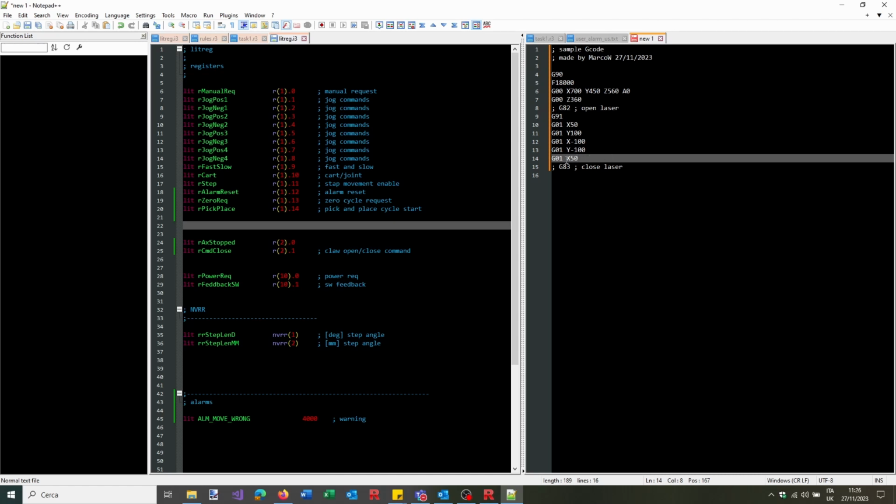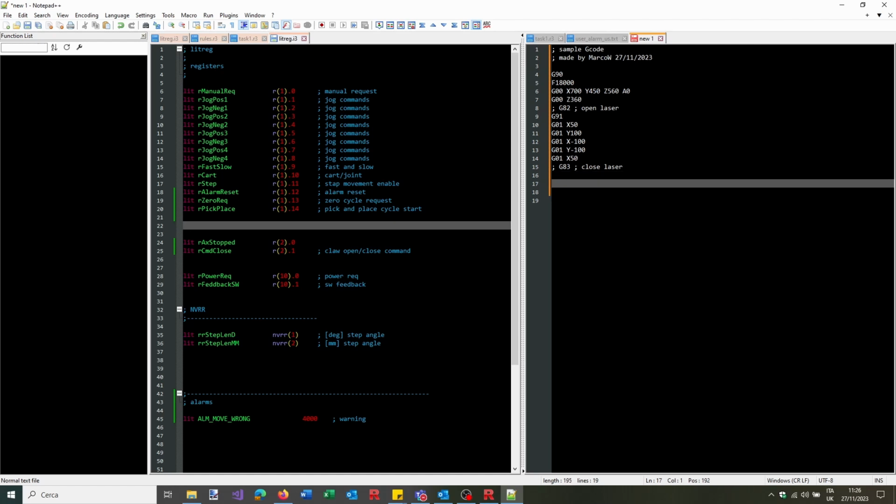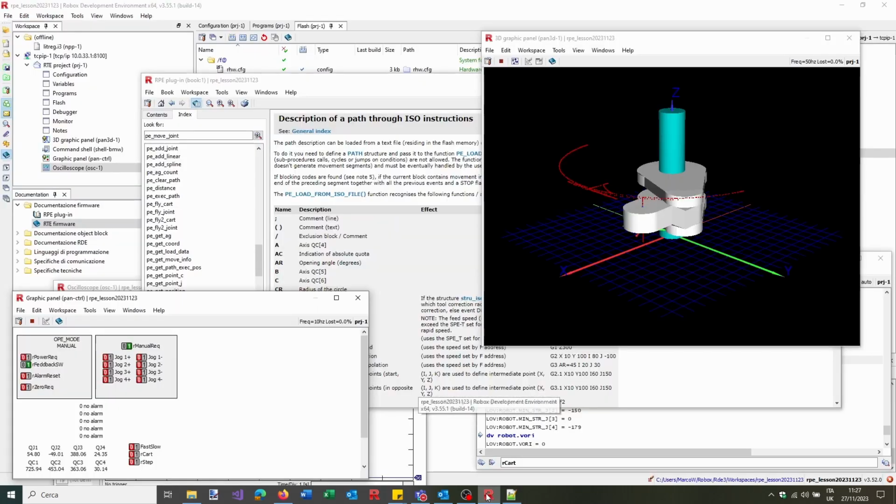Of course, sometimes these can overlap the begin point, and so maybe going more than 50 in case you want to weld or paint more than the initial point, because sometimes also the open and close of the tool can have some delay, but this is something depending on your machine. Now that's just a sample, so we finish, and then I say okay, M30 or normally M2 is also more standard to say that the path is closed.